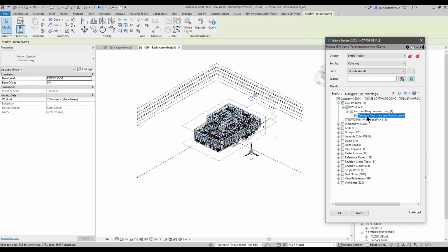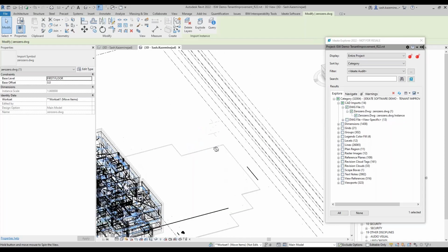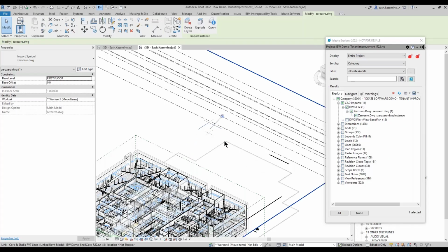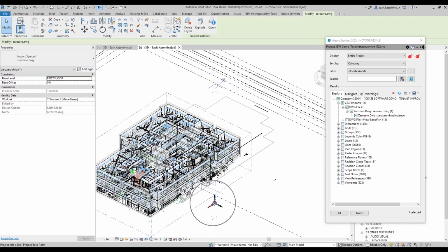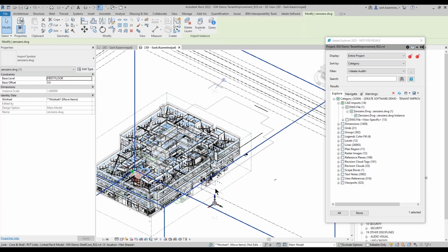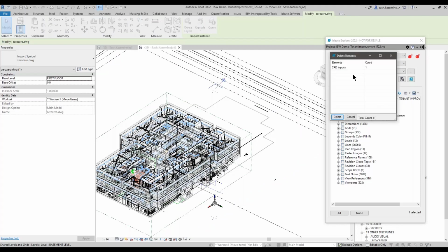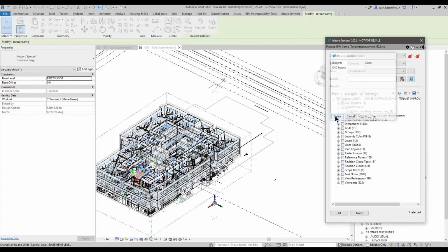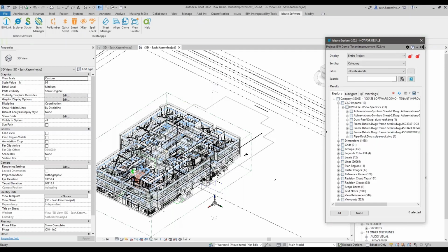Like I have this one over here called 00, and if I double click on it, clearly somebody put a marker in here using an imported CAD file to represent where the origin point is in the Revit project, although it's nowhere close. The origin point happens to be over here, so this isn't even accurate. So I can come over here, click delete, and confirm that I want to remove that CAD import, and you can see right there, it's gone. Nice way to clean this information up.